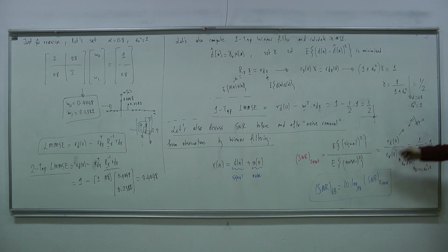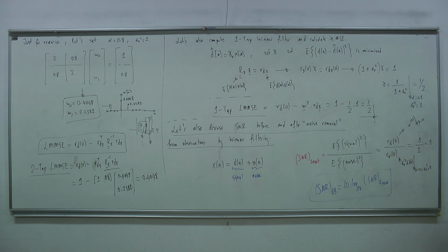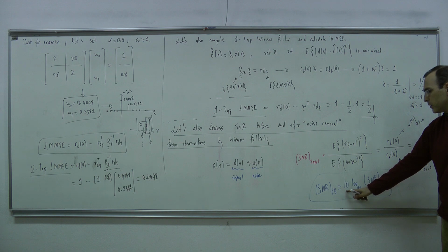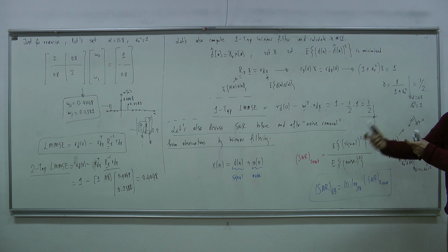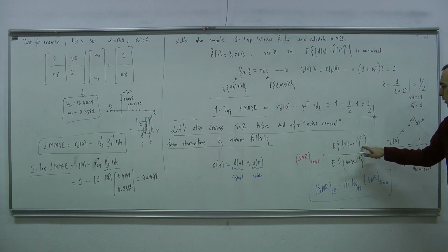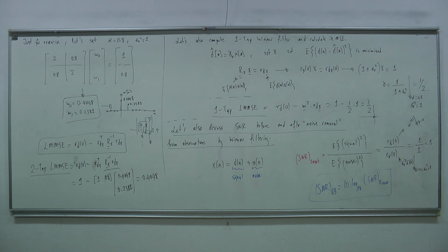This is again the same as the dB scale for, let's say, AC circuits. You may remember, for example, if you are sketching a frequency response in dB, you should be a little careful whether this is 20 or 10 or so on. But what's the reasoning behind this? This dB scale is considered from the viewpoint of dissipated power, and as you see, the numerator part is related to the power. That is the reason I have 10 over here, because it's like V squared.